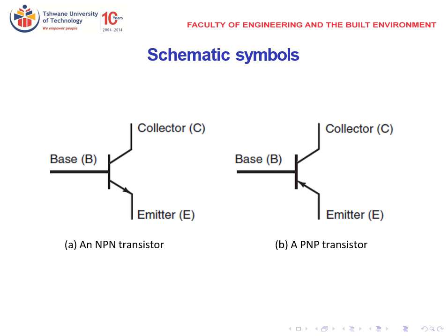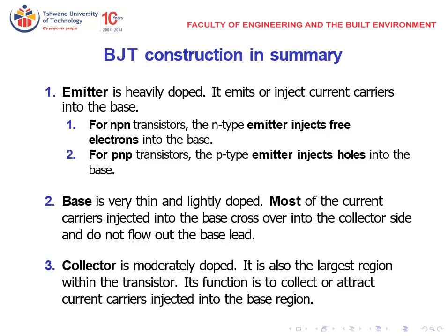But for us to differentiate between the collector and the emitter, we only show the diode between the base and the emitter. On an NPN transistor, the diodes are connected facing the base. So you have one between C and B, and one between E and B. The diode is facing inside towards the base. But to differentiate between collector and emitter, we only show the emitter diode.